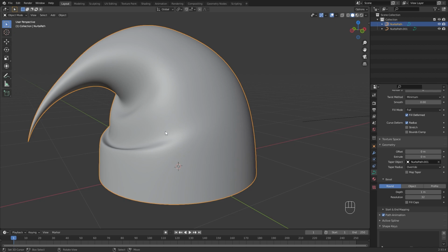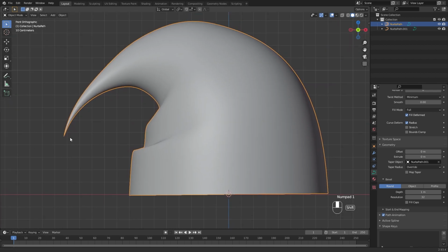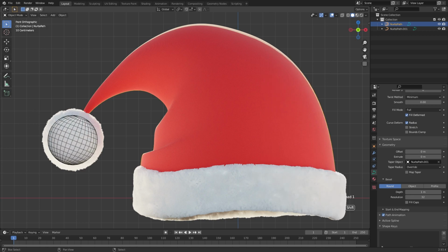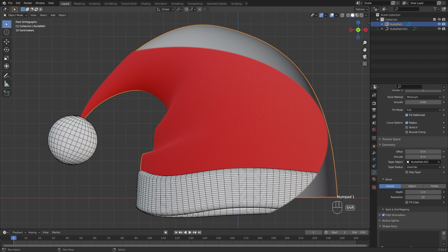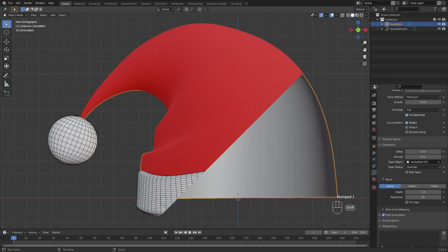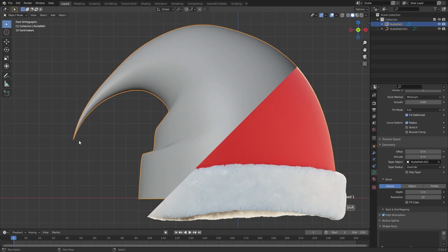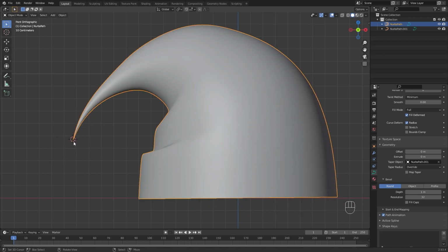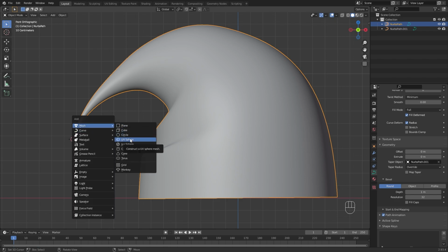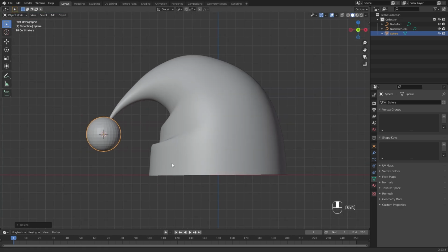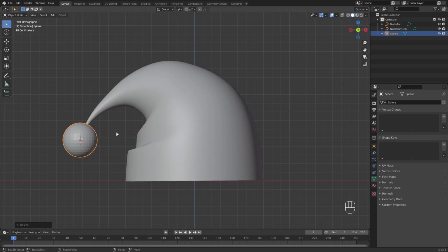Let us now create these wool-haired parts of this hat. There are 2 parts of this hat that are wool-haired. Here, we can use a sphere mesh for this one, and for the other, we have to use a ring-shaped object. Okay, let's start with this haired sphere. To do this, set the 3D cursor to the end corner of the hat and add a UV sphere. Scale this 0.2 times. Now set the shading smooth and rotate this to match the hat.